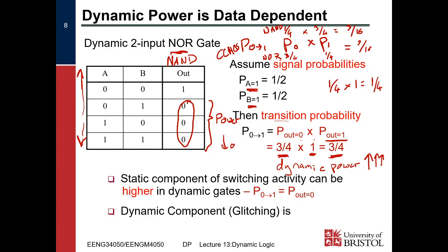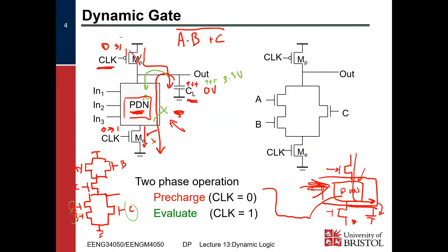And then discharging down again, right? So yes, if you're trying to aim for low power in your dynamic design, then you want to choose either a pull-up network or a pull-down network, where if your output normally stays high, you choose a pull-down network. If your output usually stays low, you want to choose a pull-up network. However, if you want low power, you're better off with complementary CMOS anyway, because the chances of transitioning are lower in the first place. Does that make sense?